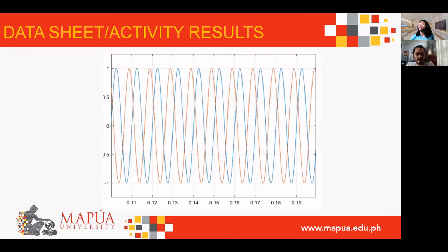So next is at 0.2 seconds. It is just the time that the LSB will be back to 0, since its period is set to 0.4. While at the same time, the MSB has already finished its first cycle and is now starting its second cycle by rising to 1, which is why the third 2-bit code is 10, and as we can see, the graph displays the result.